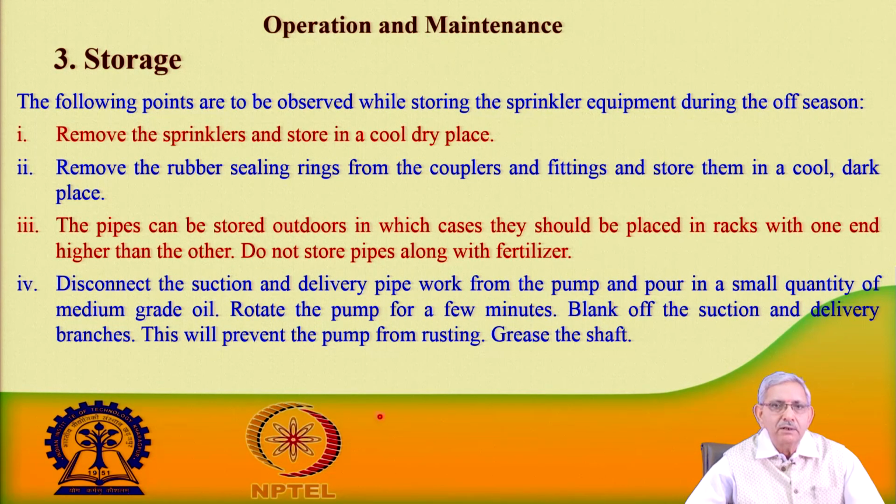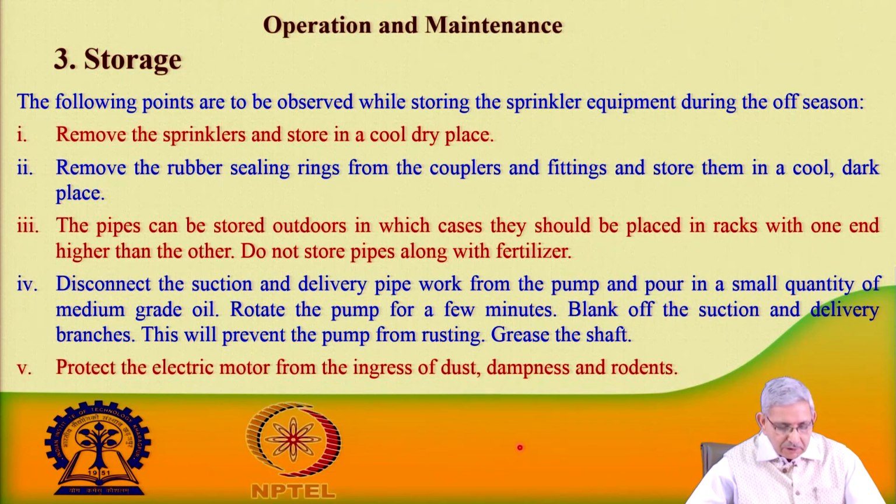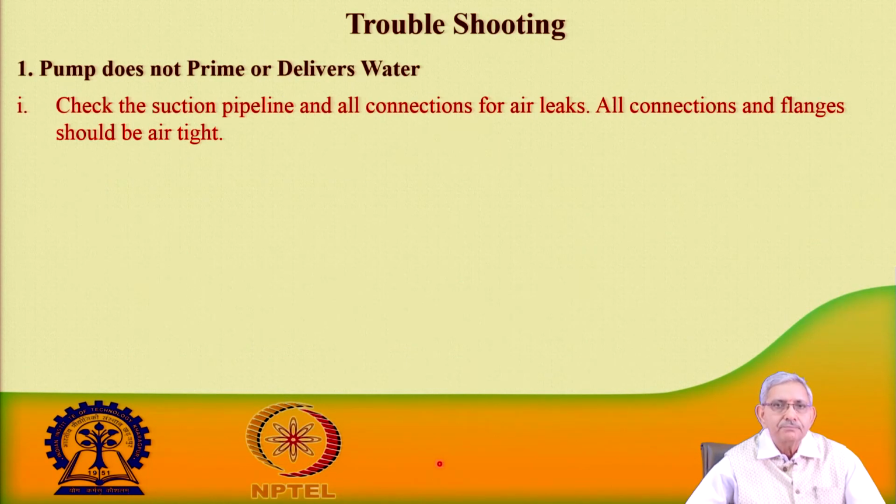So, this should be taken care of, and at the appropriate locations the grease, the shaft and the pump should be checked from time to time that it is working properly. We should protect the electric motor from the ingress of dust, dampness and rodents.